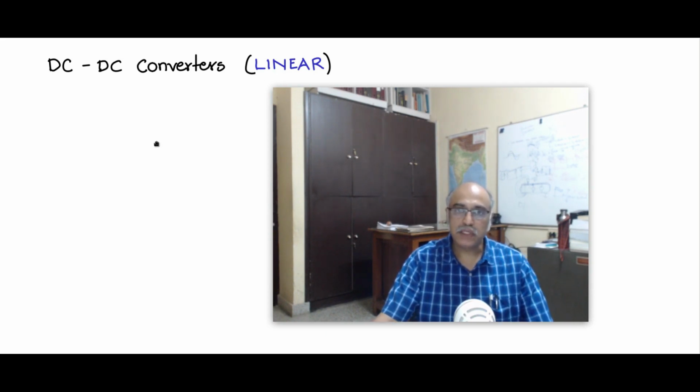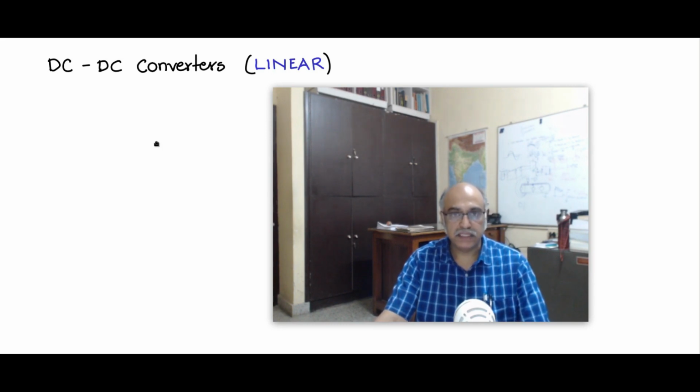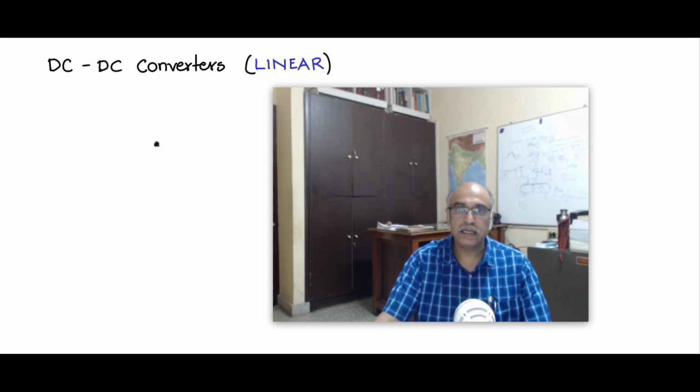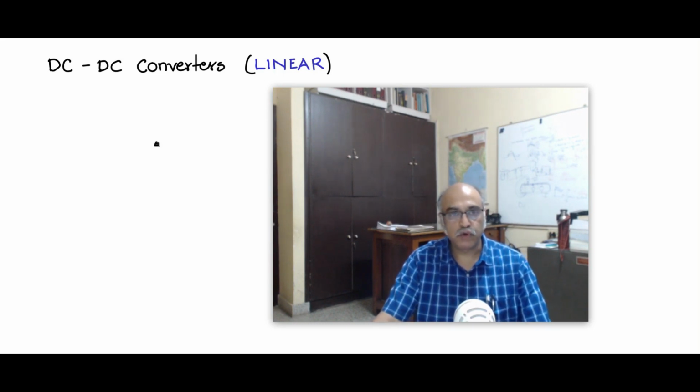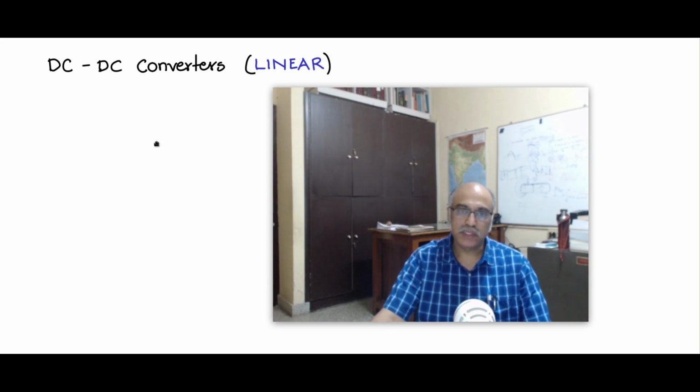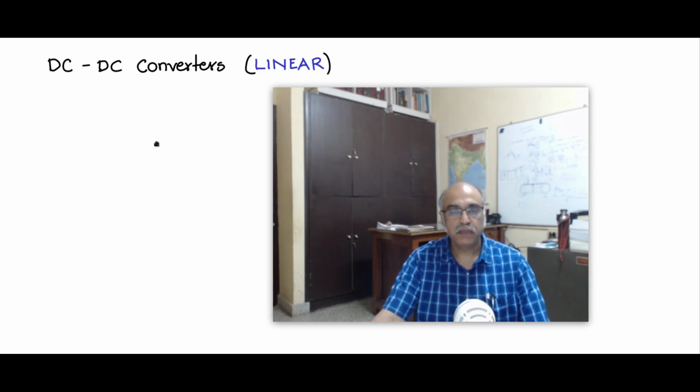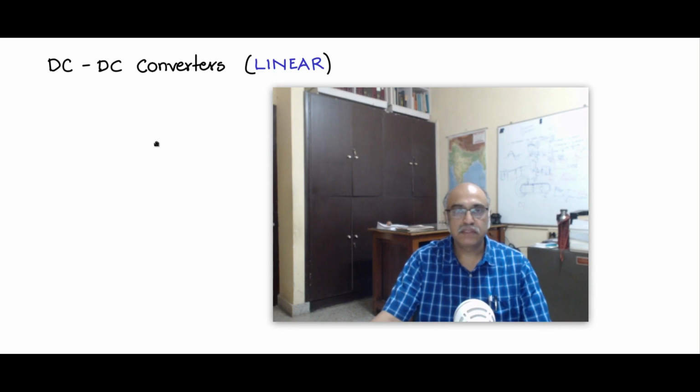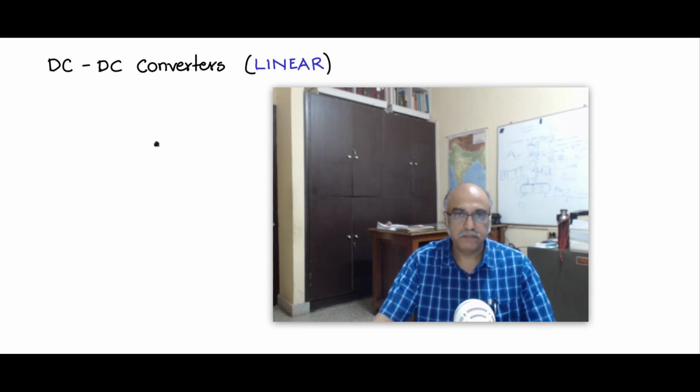The only disadvantage in the linear regulator is efficiency. It is very lossy. It cannot match the switched mode power converters with respect to efficiency. As a consequence, the linear regulators are bulkier and costlier.